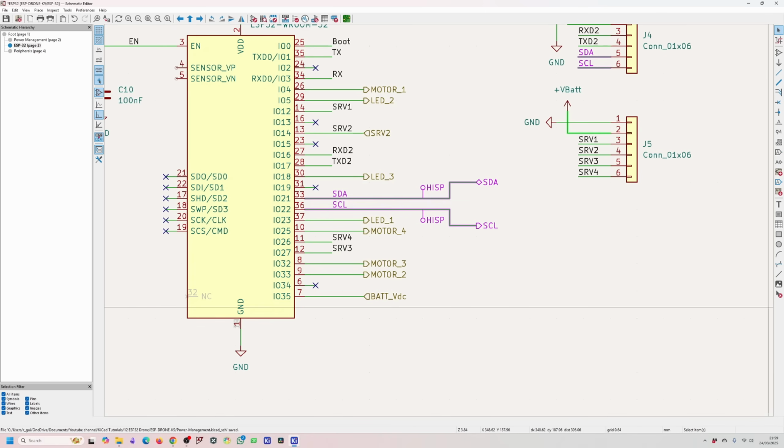You can set up your default class so that it's not violating any requirements from, let's say, PCBWay, which is the company that's going to be manufacturing this PCB. So if we set up our default to meet their minimum requirements, which may be their minimum low cost requirements or minimum high cost requirements, that depends on the project itself.